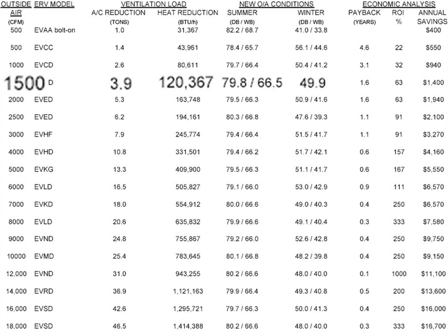A question came in from Michael about hotel/motel applications with shafts serving multiple exhaust ventilation. Those systems are not very well suited to ERVs, not just high-rise hotels, but also condominiums and apartment buildings that are multi-story with individual exhaust fans. The problem with anything with individual exhaust fans is that I can't get all the exhaust air near the incoming air. If I have a centralized exhaust fan in those buildings, then it's much more feasible, and it's very doable in those cases.